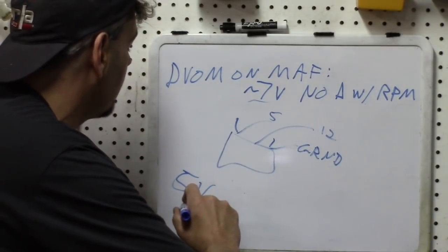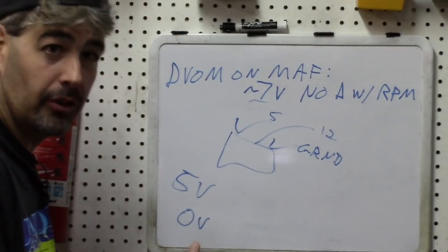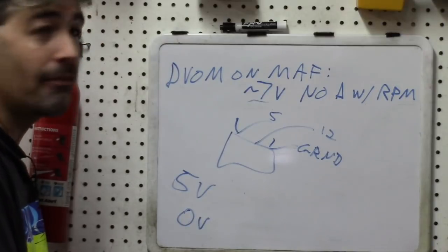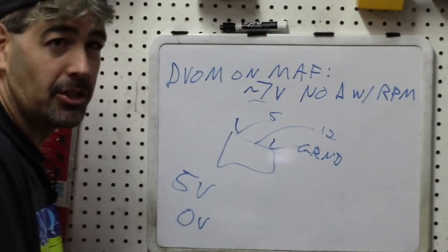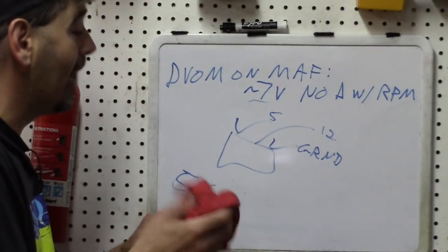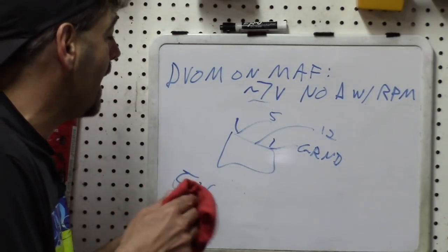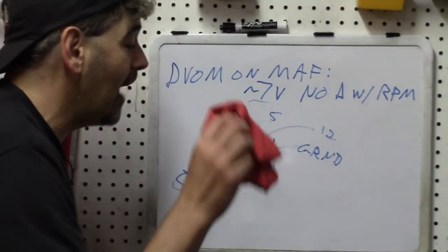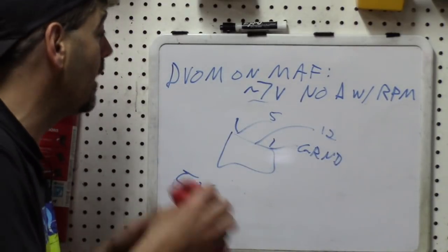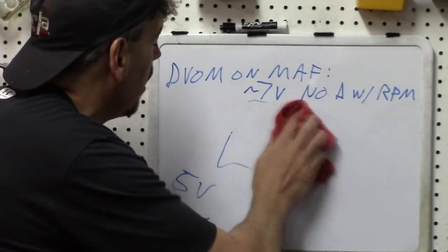And if he had read closer to 0 volts, then almost certainly it would have been an analog MAF. But because it's pretty clear he didn't measure the ground, we don't know that. As a matter of fact, we don't even know that the ground is good, except that a bad ground would have certainly caused a mass airflow error code as opposed to just a lean code.